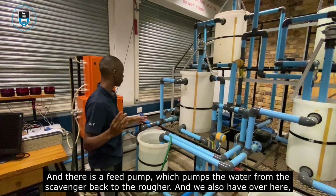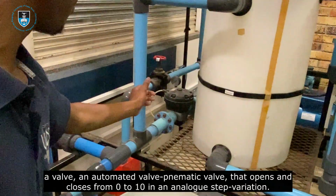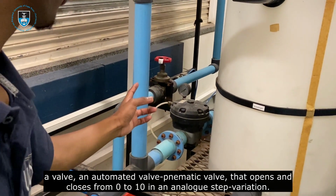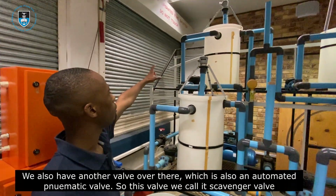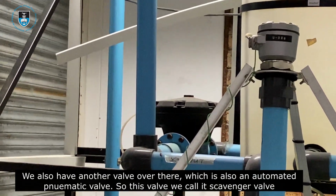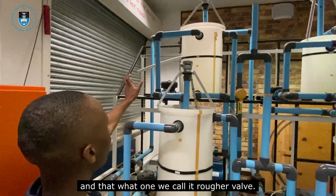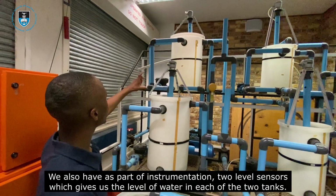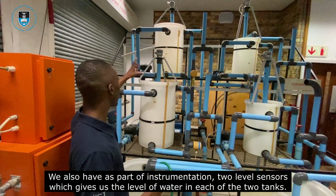And you also have over here a valve, an automated pneumatic valve that opens and closes from 0 to 10 in an analog step. We also have another valve over there, which is also an automated pneumatic valve. So this valve, we call it the scavenger valve, and that one we call the rougher valve. We also have, in the part of instrumentation, 2 level sensors, which give us the amount of water in each of the 2 tanks.